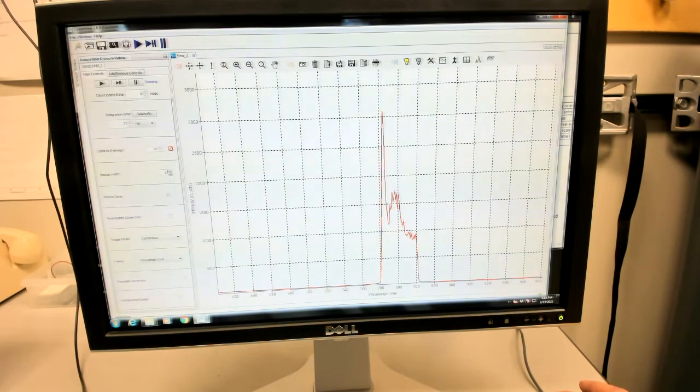So if I change this, say, to 4, then it will smooth over a window of about 4 pixels. That's useful so that we don't get caught up in the tiny details. So I'm going to suggest you use a boxcar width of around 4. The other controls we don't need to look at. Very good.